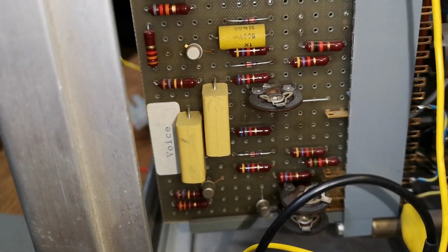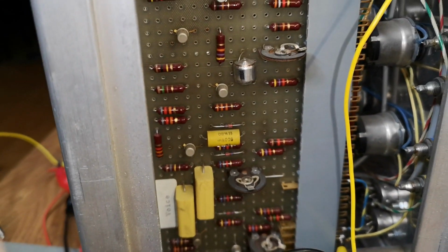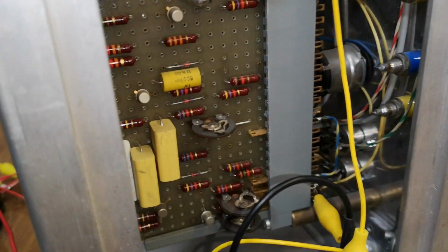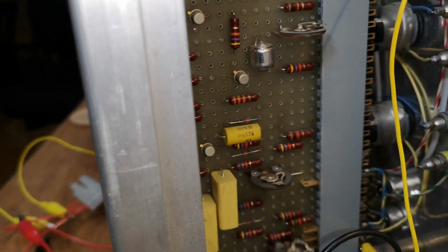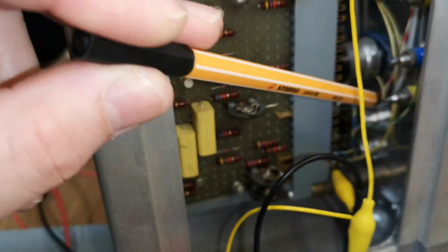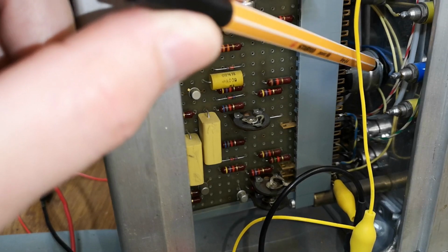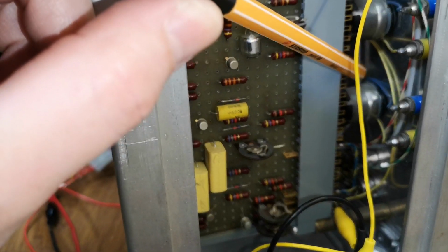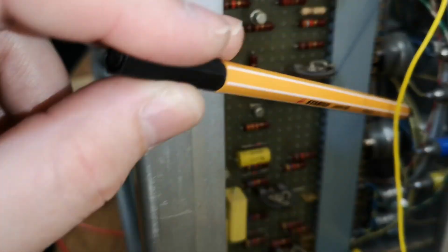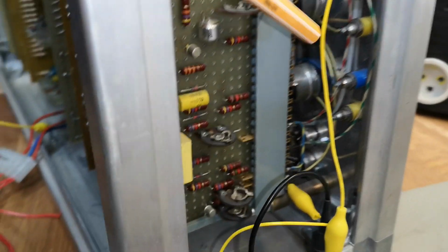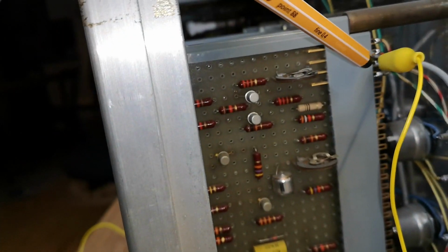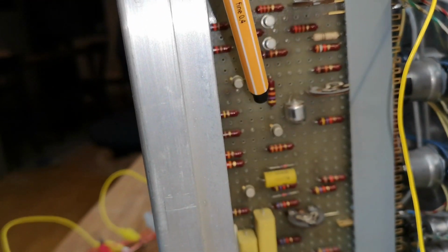So this is the fundamental frequency or pulse generator, because this is a pulse generator, and it takes the voltage input from a potentiometer here. It goes via a switch where you can enable or disable the manual override. Else, of course, you take the banana inputs. So this is the voltage input, and this is the pulse output of this module.